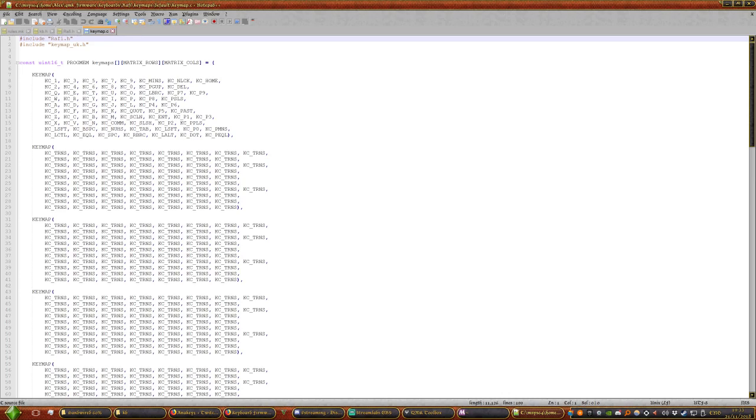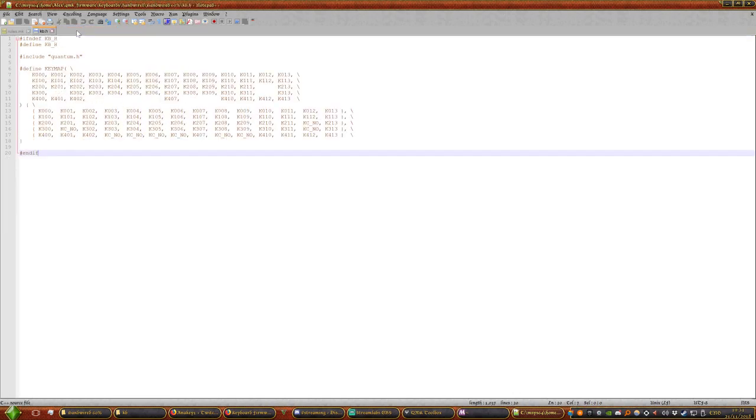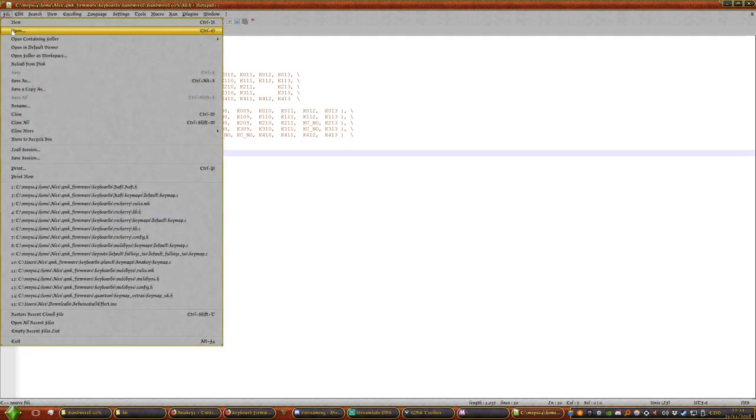So it's not in a traditional sort of rows and columns like you would normally have. So it's something to look out for if you do decide to obviously convert your vintage keyboards, which I might do a small series on in the new year as to how you would go about converting a vintage keyboard that is not XT or AT compatible. So if, say, it uses an odd protocol or for some other reason isn't directly compatible, then you'd have to obviously basically just figure out what the matrix is and then try and program it yourself onto an external MCU. So we'll go back. So this is, like I said, this is what the KB.H is. And I'll also show you my UK78 as well as another example.